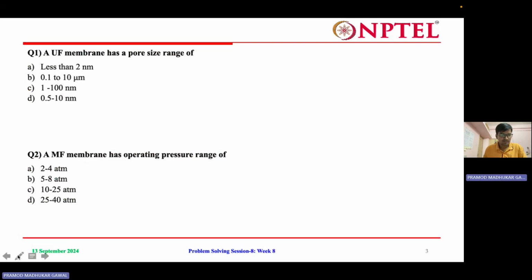Starting with the MCQs, question number 1: the ultrafiltration membrane has a pore size range of? Option A is less than 2 nanometers, B is 0.1 to 10 micrometers, C is 1 to 100 nanometers, D is 0.5 to 10 nanometers.